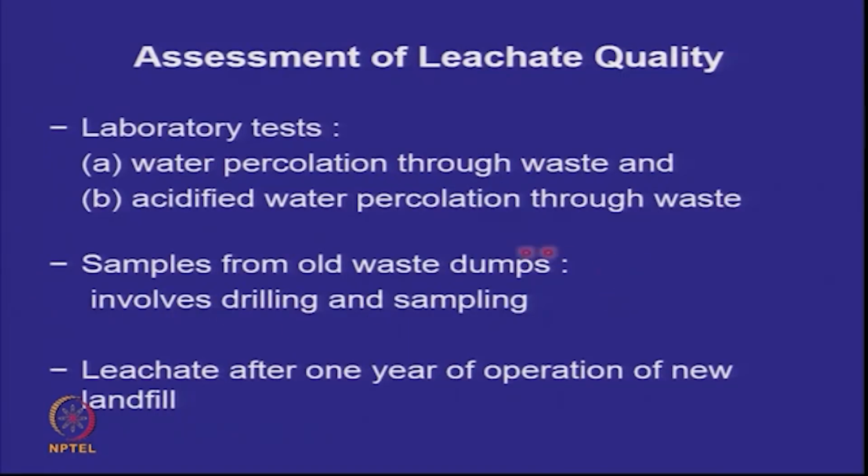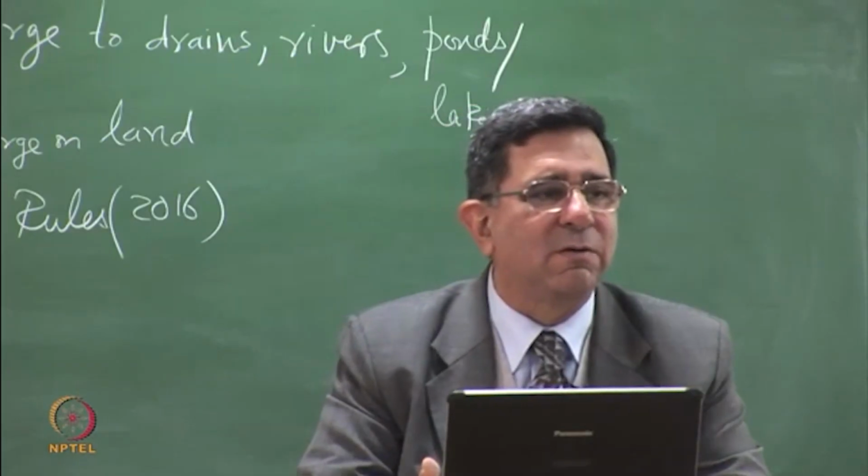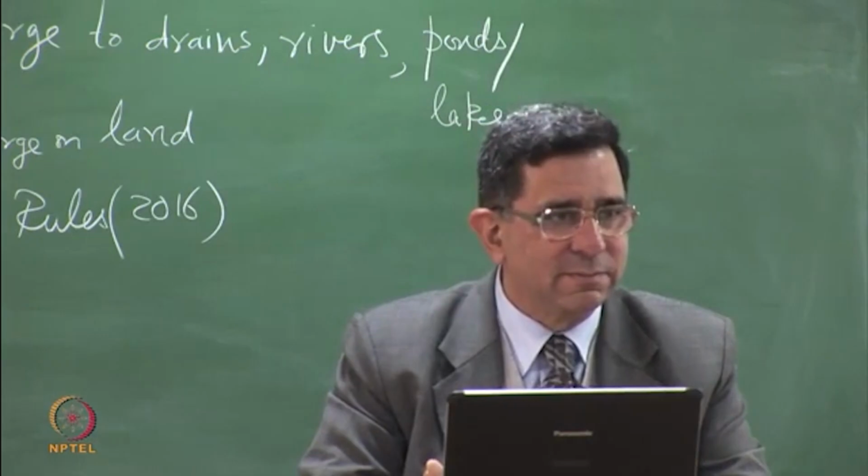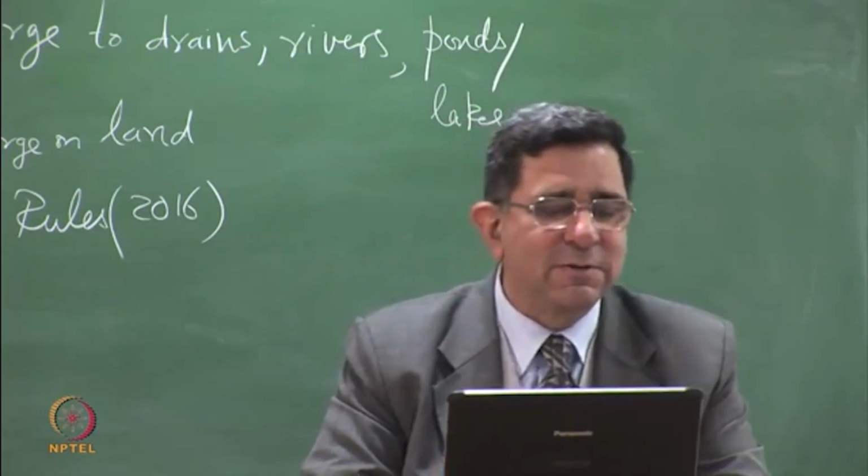So why is this important? Because we need to treat this leachate in the end. If I don't have a handle on what the constituents are, what treatment plant am I going to make, right? So I'm going to treat this in the end.